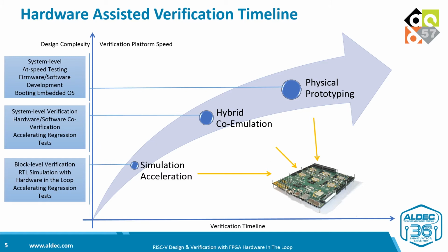If the firmware function needs to read a peripheral register, it gets real data instead of fake or stubbed one as in a pure ISS simulation environment. If the register value is unexpected, for example, now the software team can consult with the hardware team to debug this case together. The bug needs to be fixed either in software or in hardware, and with hybrid co-emulation they are detected and fixed much earlier, and they can be corrected before the chip is taped out.